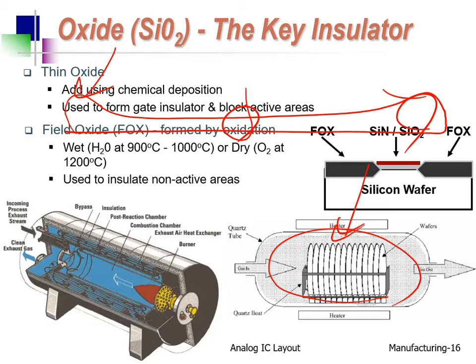So how about the performance of your MOSFET? If you have a MOS here and another MOS there, I promise you, the conductivity here is much better than there. That is the so-called systematic mismatch. So, for your layout, if you would like to match two of them, or many of them, please, according to such systematic mismatch, they had better be laid out close to each other. Okay? The closer to each other, the better.